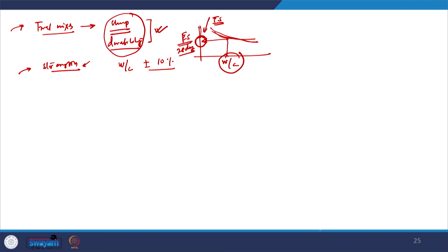Okay. In the same situation, if we are making a ready mix concrete, which means we are making it in a plant and that has to be transported to the site, then we have to again further do some adjustments. So, there we have to first understand what is the distance between the plant and the site. Let us say if the transit distance is so long that you will need more than 1 hour to reach from the plant to the site.